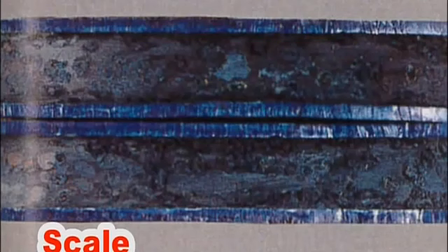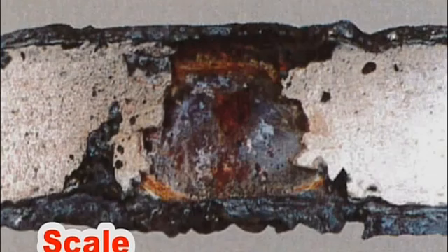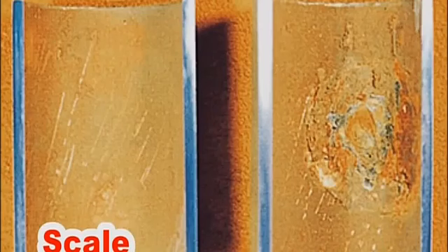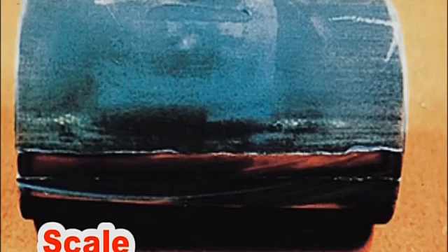When feed water impurities are subjected to thermal decomposition and chemical reaction, they produce water-insoluble substances. Some of these substances adhere to a boiler's internal heating surfaces in the form of hard scales. Scaling degrades a boiler's heat transfer performance and, through hotter surface temperatures and overheating, can cause pipes to swell and bend.